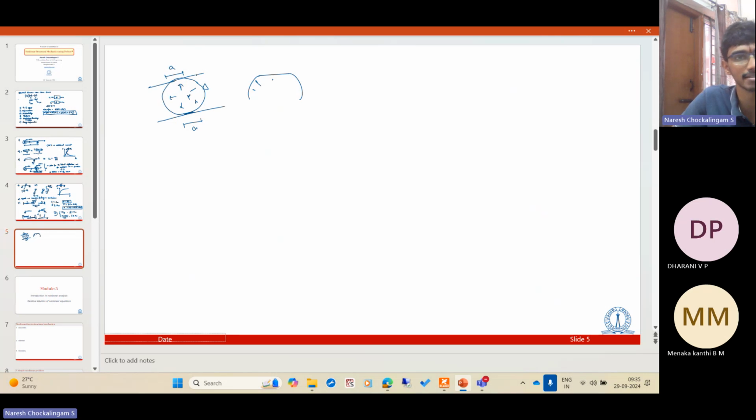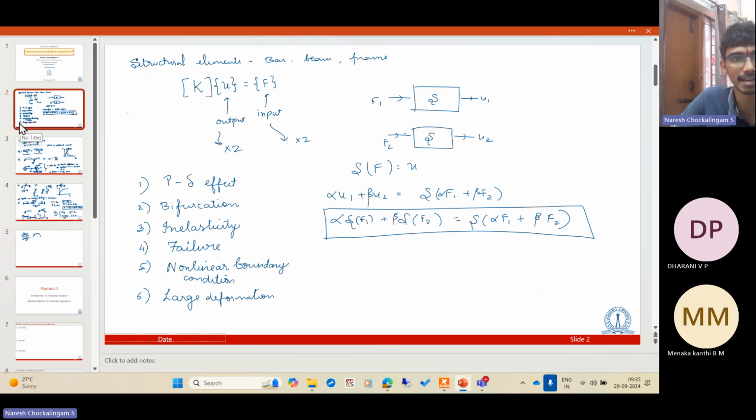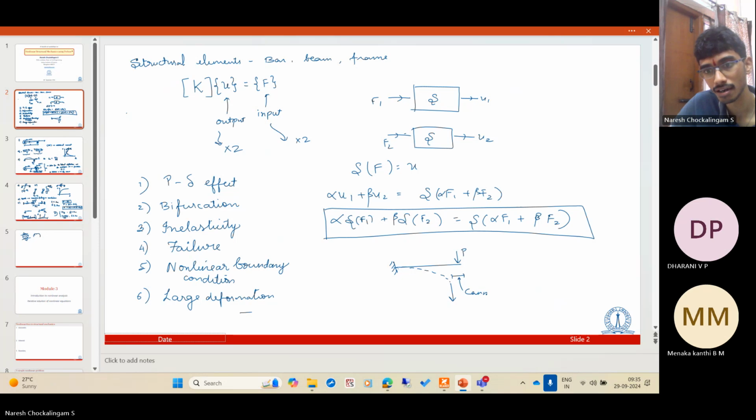So contact problems arise in various applications in mechanics. In the context of structural elements, rod-like elements, there are some special cases where it occurs. Then you can have all kinds of large deformation. That is where we started this workshop. I said we have a cantilever beam with a tip load, and as it deflects, you will have the beam bending in this way. And as it bends, the tip of the cantilever will be retracted towards the wall. And this cannot be calculated by linear theories.